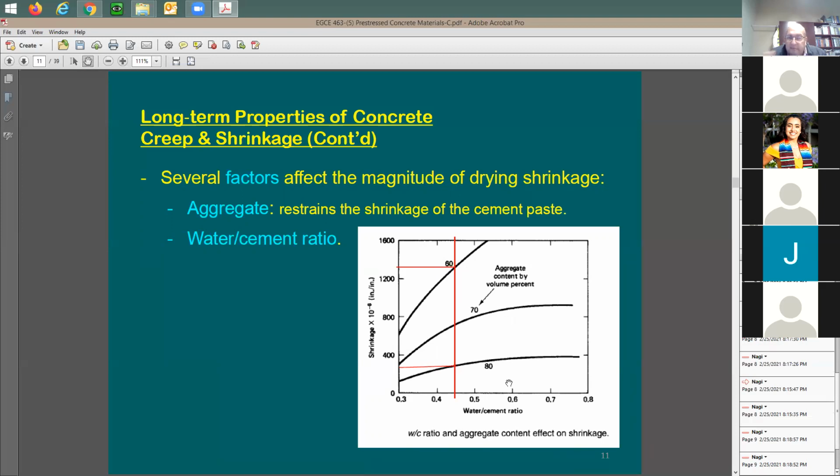Professor, when you use larger aggregate in concrete, you get less surface area of the aggregate, right? So does that mean that it weakens the concrete? When you go to smaller aggregate size, you're going to have bigger surface area, and the effect of the aggregate itself to reduce the shrinkage is going to be higher.